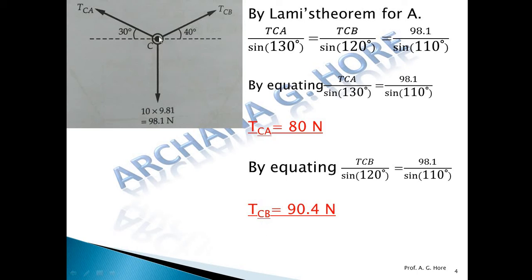So first of all draw the FBD. Steps are: FBD, count the number of forces, and according to that use the condition of equilibrium.